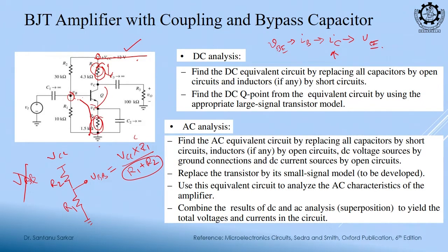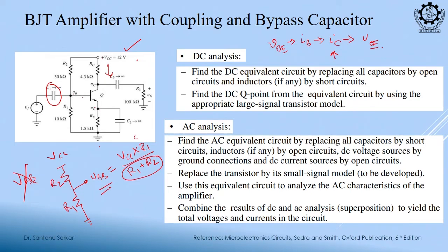Now, see, some capacitors are drawn there. We discussed this. They are known as the coupling capacitor, or bypass capacitor. So, what is the job of this capacitor? To couple the AC signal, and why is it placed? We discussed this. Now, I have properly found the VBB, and I do not want to disturb this Q point. So, this AC source should start from 0, and it is an AC signal, but I do not know, it may have a DC portion also, I am not sure.